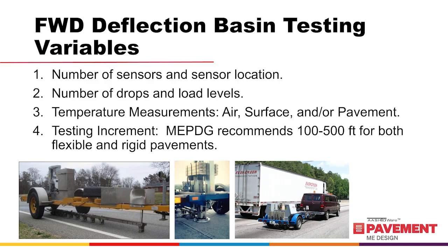of the PCC slabs. Within the LTPP program, pavement temperatures were measured, but for routine pavement evaluation and rehabilitation design, pavement temperatures are rarely measured because it takes a lot of time and effort to measure pavement temperature. As a minimum, however, the air and pavement surface temperatures are recorded. These 2 variables can then be used to calculate the pavement temperature for use in rehabilitation design.